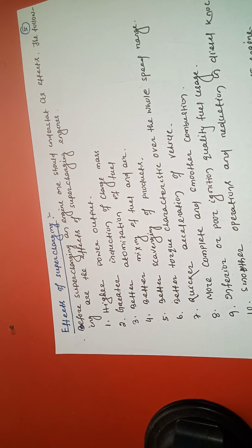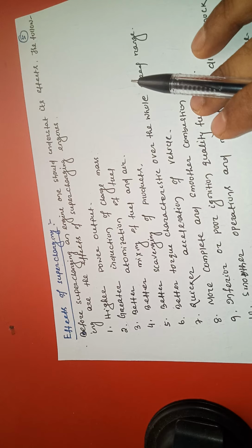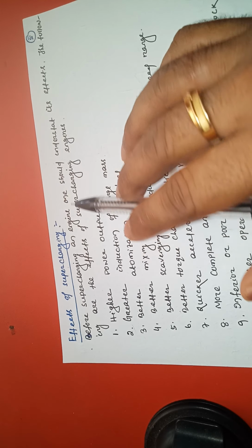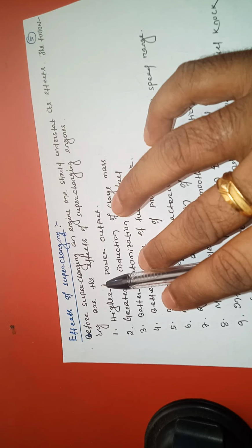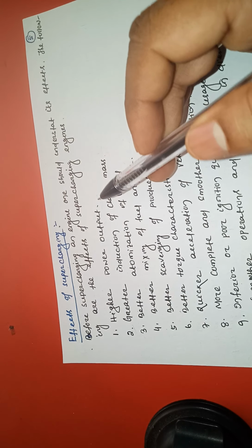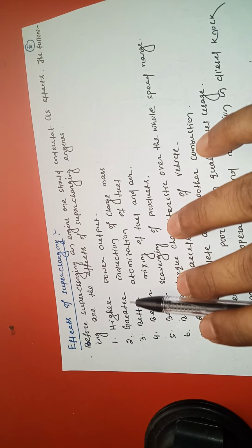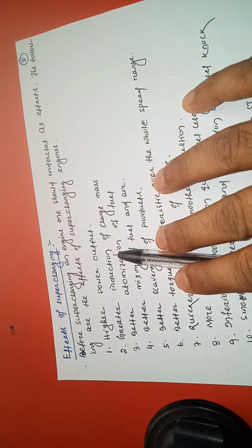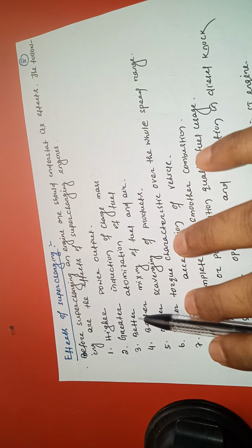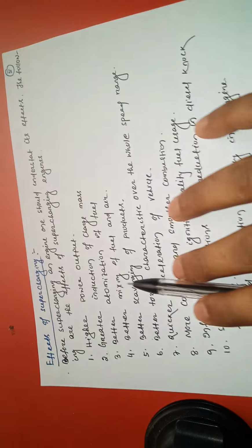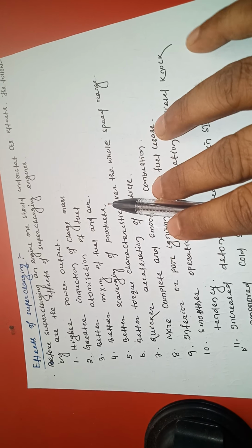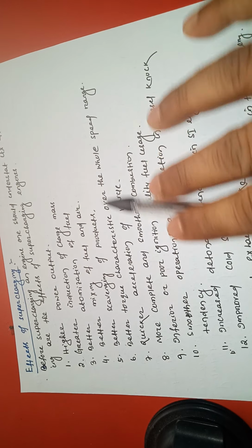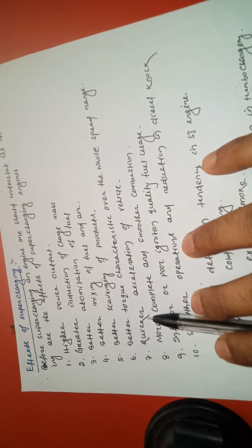Next one is effects of supercharging. Before supercharging an engine, one should understand its effects. The following are the effects of supercharging engines: higher power output, greater induction of charge mass, better atomization of fuel, better mixing of fuel and air, better scavenging of products, better torque characteristics over the whole speed range, quicker acceleration